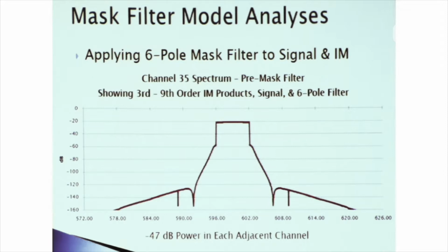But the real data ends at this spike, and that'll be constant throughout these images. So and then here's the 8-pole filter, and you can see that the total from here to here is minus 57 dB of the power in this channel, essentially up here. And again, this flat top is 20.79 down.